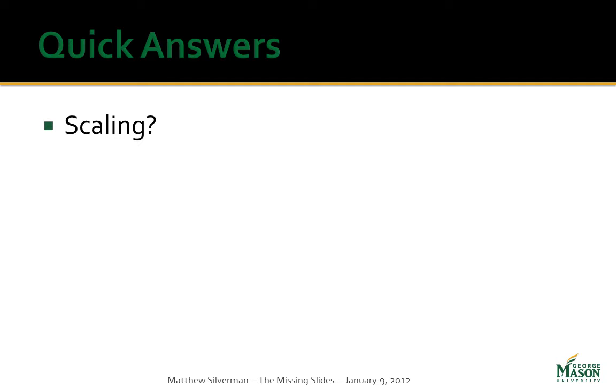Generally, you can handle scaling in one of two ways. You handle it at your projector, or you handle it via a component, a scaler within the system. Both are valid depending on your application. With our first design, we chose only to scale at the projector. The projectors we use are 1280 by 800 native, and we found they can pretty much scale any signal coming in up to about 1080. The only thing they don't seem to handle well is 1920 by 1200.